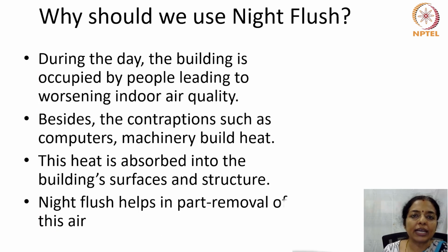Why should we use night flush? This is important. During the day, the building is occupied by people, which leads to worsening indoor air quality. So the indoor air quality becomes poor because of buildup of carbon dioxide and carbon monoxide because of breathing. Besides, there are contraptions such as computers and machinery, which build heat. This heat is absorbed into the building's surfaces and structure. Night flush helps to partly remove this air.